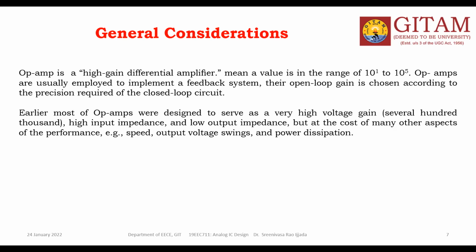These are the basic requirements of an operational amplifier, or any amplifier. At the same time, while designing to improve the gain or the input impedance or to reduce the load, we lost some parameters. What parameters did we suffer on when we concentrated mainly on these three? Speed, output voltage swing, and power dissipation. So the designs happened like that earlier.